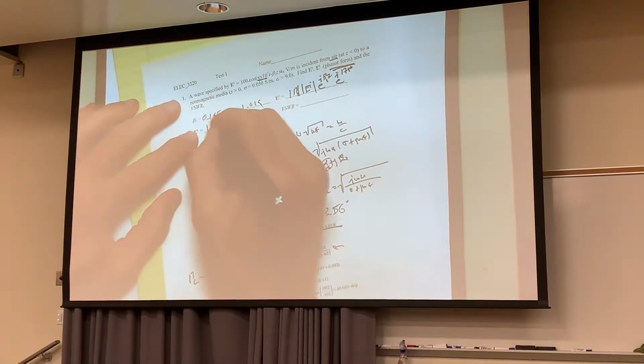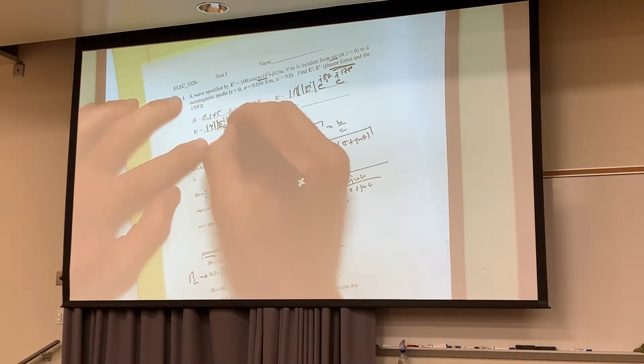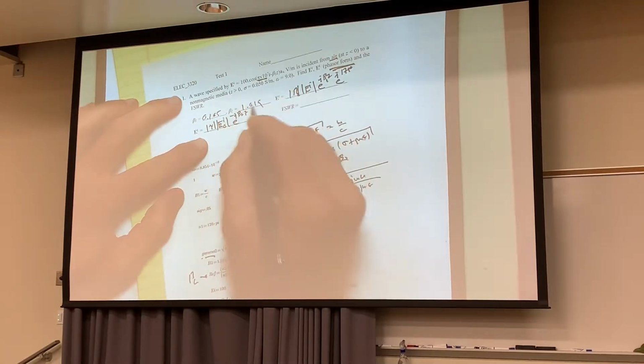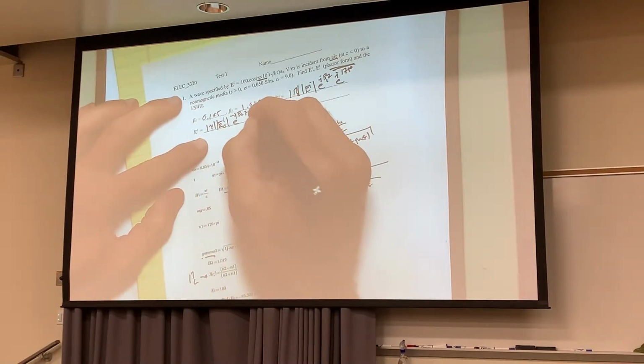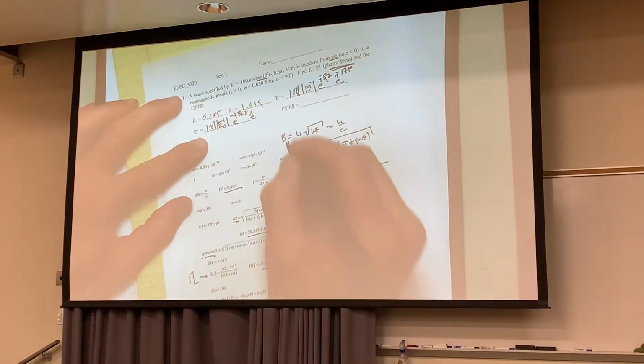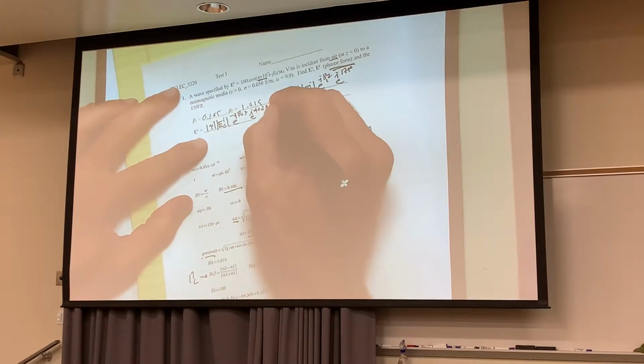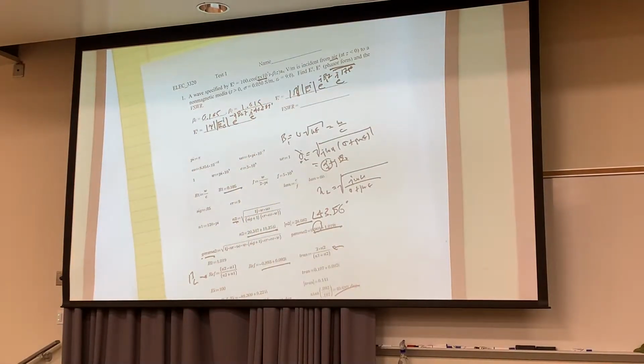This is going to be the magnitude of the transmission coefficient times the magnitude of E naught incident. Then it's going to be e^(-jβ2 z). That's this beta 2. Then it's going to be e to the j, and now you've got to get the angle of this transmission coefficient, and that's 40.689 degrees, I believe. And it's plus j 40.689 degrees. Are you with me?